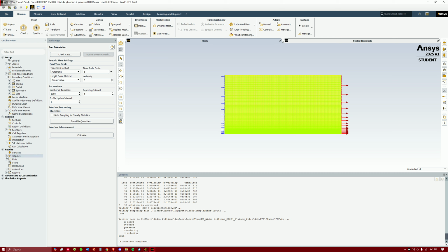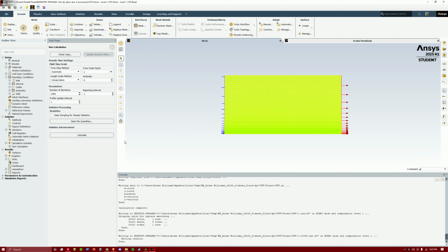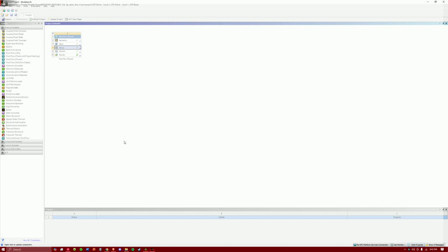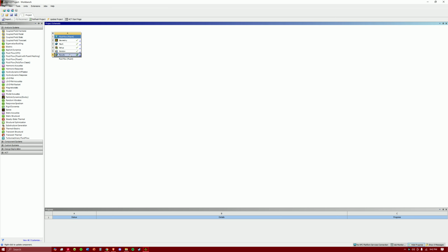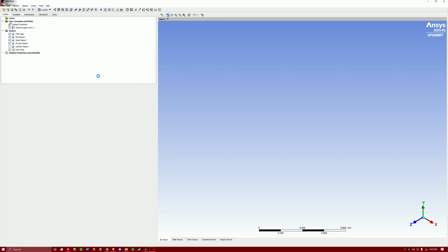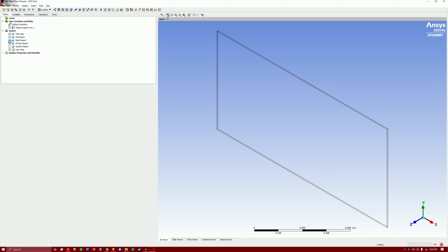So now that you have that, we can start with the first part. The first part asks for velocity with vectors and pressure contours around the flat plate. And because it asks for vectors, we're actually going to exit out of solution, just because I think the contours and the vectors look much nicer in the results section, the results app of Fluent. So just pop open results.